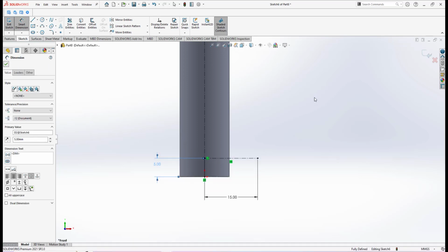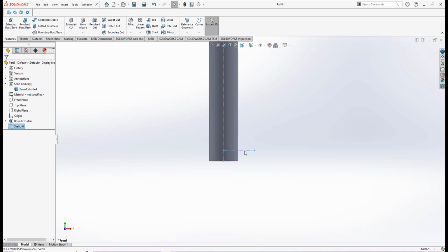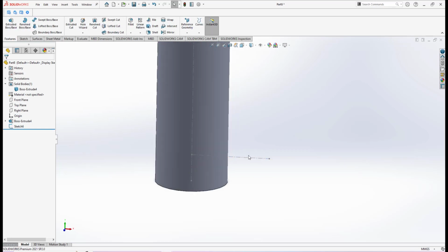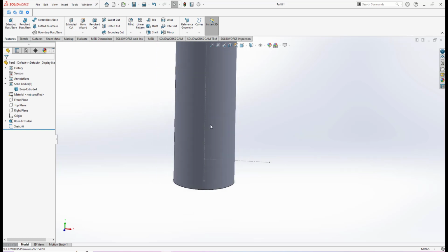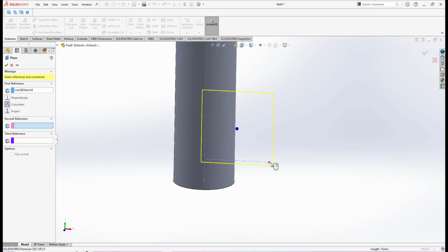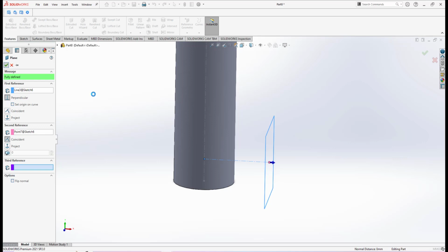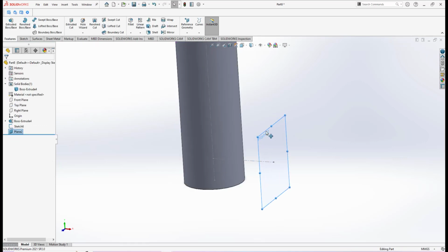The idea of the center line is that I can create a normal plane here, so I can extrude a rectangular shape up until this body. I extrude it to this body to create the base shape of the arm. Okay, I have this line, so I can create a normal plane there. Alright, on this normal plane, I will create a sketch.